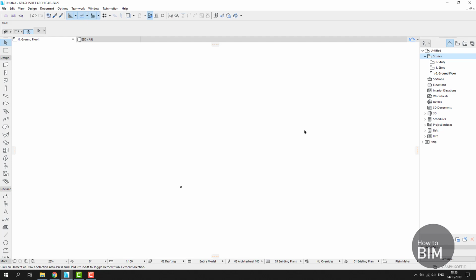As I told you, the difference between CAD and BIM software is quite huge, and in BIM we have one project where everything is connected. But for occasions when we need to import some kind of DWG or PDF, basically any kind of trace reference, we have something in the organization instruction on the right that is called Worksheets. If I click in here by a left click, I can create new independent worksheets.